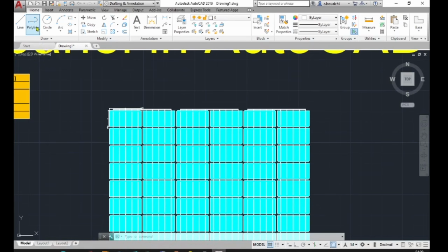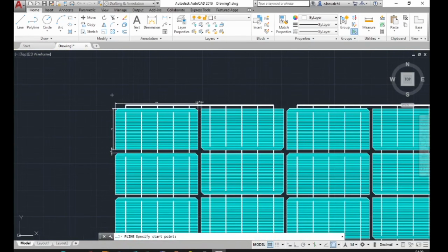Select the polyline, select the first point, and we are going another time to change the thickness of the line. Click width and select, for example, 20 millimeters. Press enter. 20 another time and press enter. It's with large thickness. Press escape.